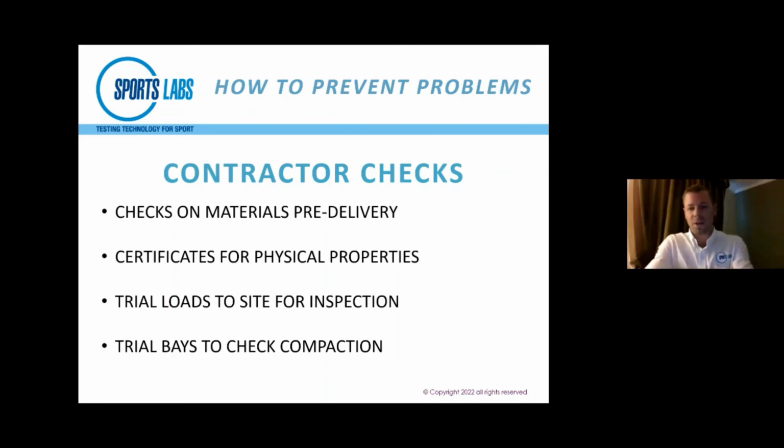And even running a hose, you've got to make sure you run it for long enough, because you don't want to just check the absorption of the stone. You've got to make sure that it's actually flowing through the stone. So running a hose for 20 to 30 minutes before you look at any measurements is really important. Don't just put it on and say, oh, it's disappearing. It's just absorption you're measuring. So it's really important to do the basics, even just with a little bit of care.